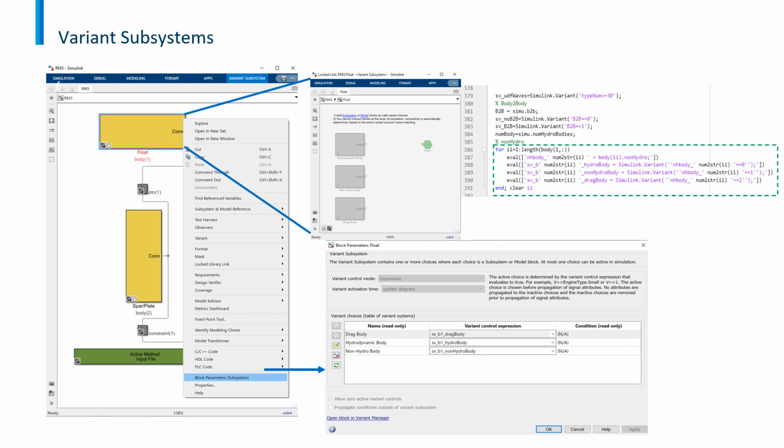On the other hand, the non-hydro body is a body that is part of the system and affects the system dynamics, but whose hydrodynamics do not necessarily affect the system dynamics. Do note that the weight and buoyancy of a non-hydro body is still considered. An example of such a body would be an anchor or parts of the system above the surface of the water.